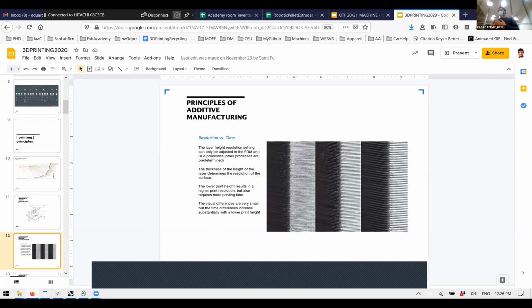For example, Nutella is a really easy chocolate. It's quite an easy material to print. The drawback is that you need to heat it up, and you only have working time while the material is still hot in the cartridge or the system. When it gets cold, you will get a jam. You could solve it by making this cartridge a little bit hot with a heating system that doesn't get too high. Yes, but it gets a little bit more messy. So we try not to print with heat-assisted things, just because it's less messy.